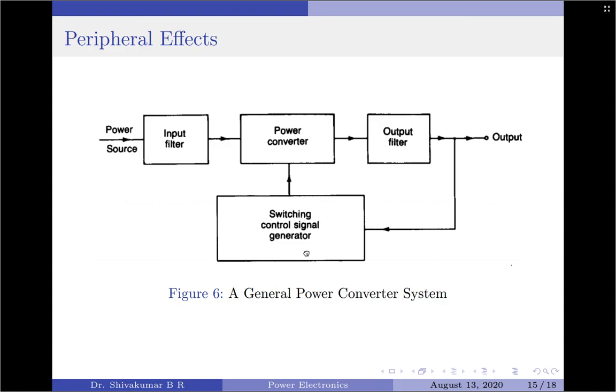The control strategy for the power converters plays an important part in harmonic generation and output waveform distortion, and can be aimed at minimizing these problems. The power converters can cause radio frequency interference due to electromagnetic radiation, and the gating circuits may generate erroneous signals. This interference can be avoided by grounded shielding.